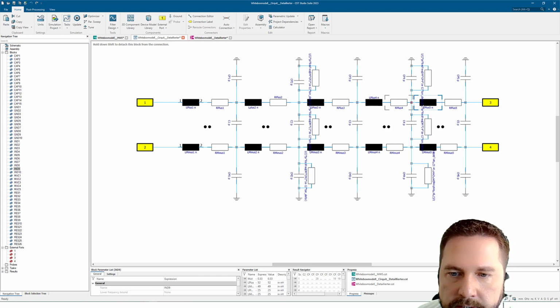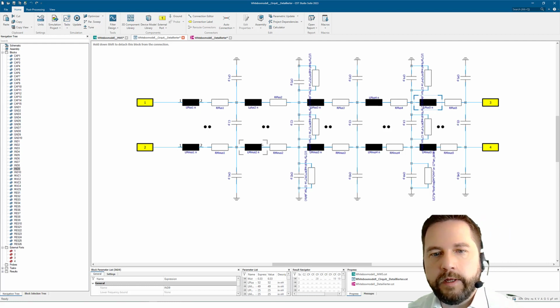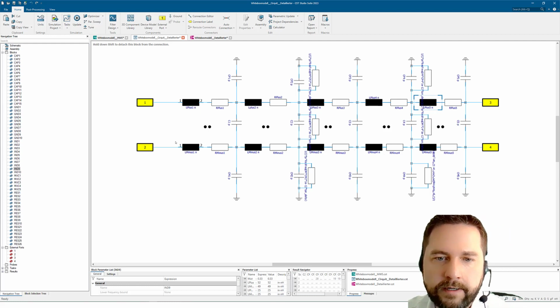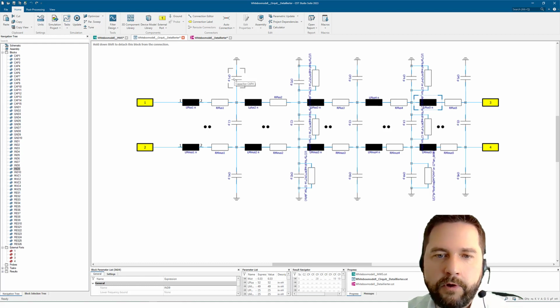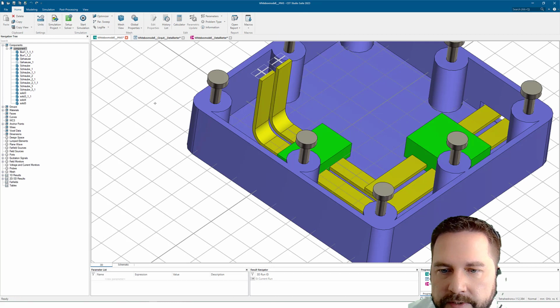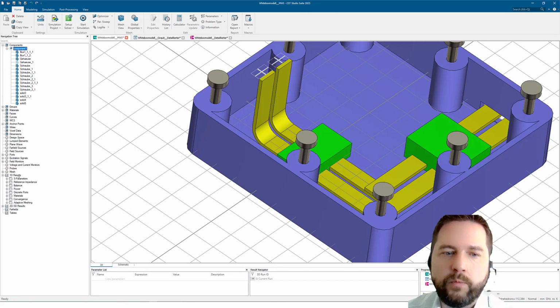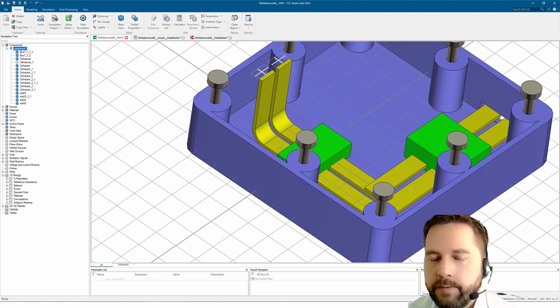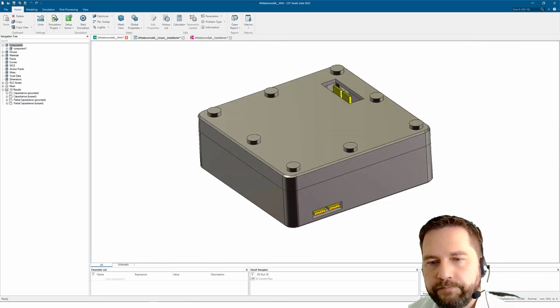But as you see here, this is a typical RLC network that we would like to build. We have some local L's and C's, so those are partial inductances and partial capacitances, the so-called parasitic capacitances, which we have to put some values in. How to get the values? Of course, it's possible to use the full wave solver and the Y parameters and the Z parameters, but that's not quite easy because we always have the complete current loop in.